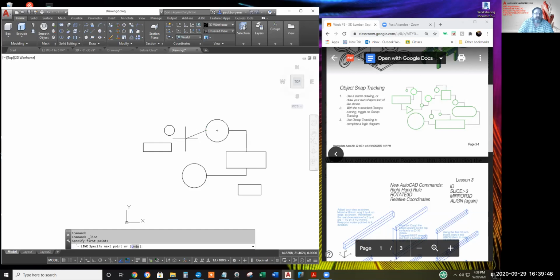Okay, that's interesting. I do not see polar tracking at a 45-degree line. It appears to only polar track with 90. Let me turn object snap tracking on again. Okay. Now with object snap tracking turned on, it obeys the 45-degree angle as well as the default 90-degree angle.